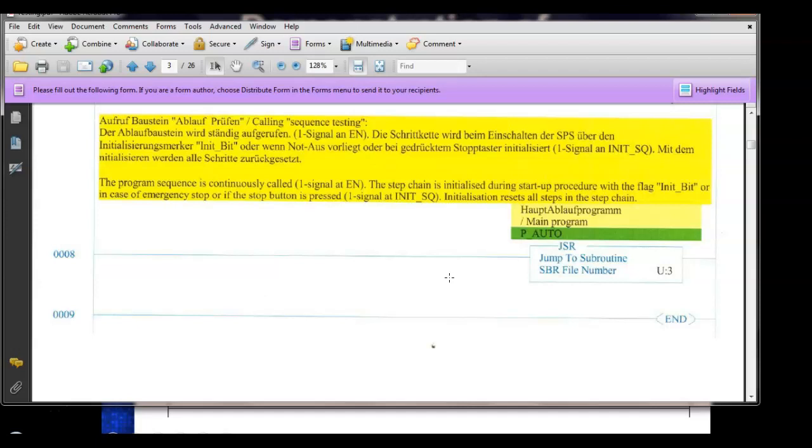So if I have problems with it missing the spring, I don't have to find that section in my main program. I just look at the subroutine and readjust my points on the robot, without trying to find it inside a big old program that's 400 lines long, right? You understand?